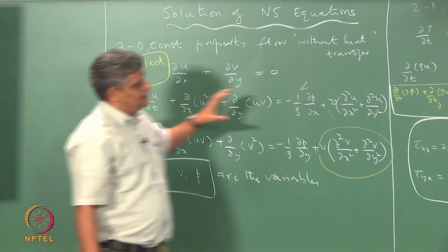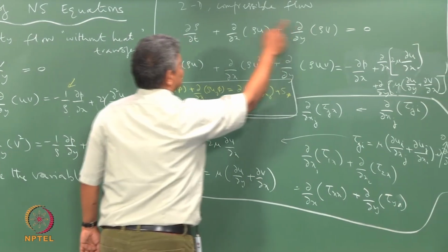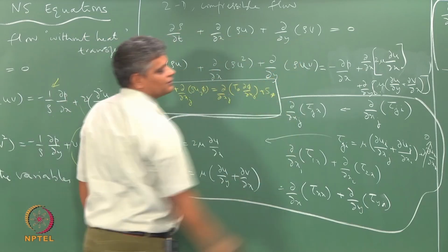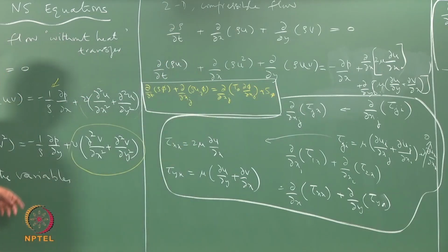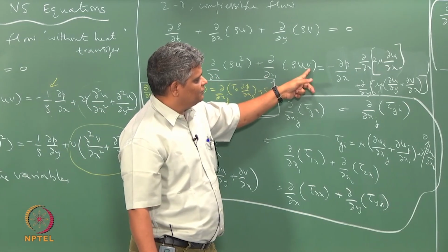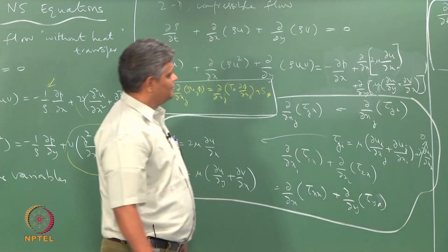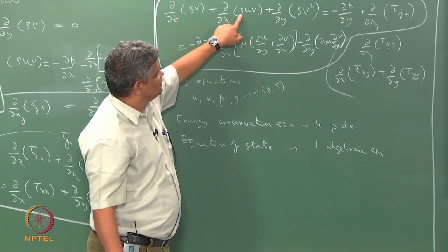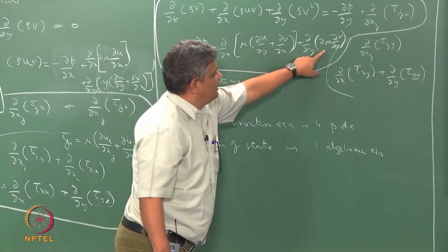and nonlinear equations. Now you come here in this particular case of compressible flow, again you have the same situation, that this equation here is involving three variables, rho which is not known, u which is not known, and v which is not known. So you can solve this only for one variable, and the other two are coupled to the other equations that are present. And again here you have u here and rho, nonlinear term here, coupled term here, unknown term here, whereas this part is known but this is coupled. Similarly, the y momentum equation, again you have unknown terms here, nonlinear term here, coupled term here, and a known term here.